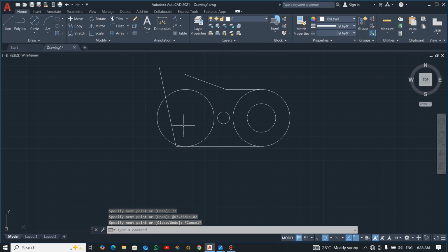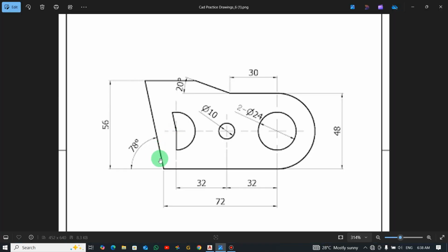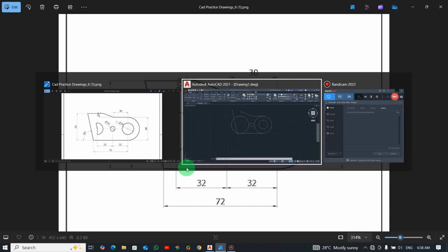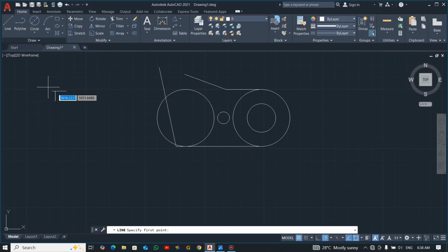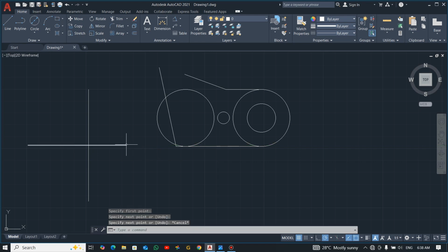Now I hope you understand. The angle is read from this place, 0. Let me create an example here. Assuming I have this quadrant, here is 0. AutoCAD reads from this side going. Angle from this side to this side is 90 degrees, so here will be 90.